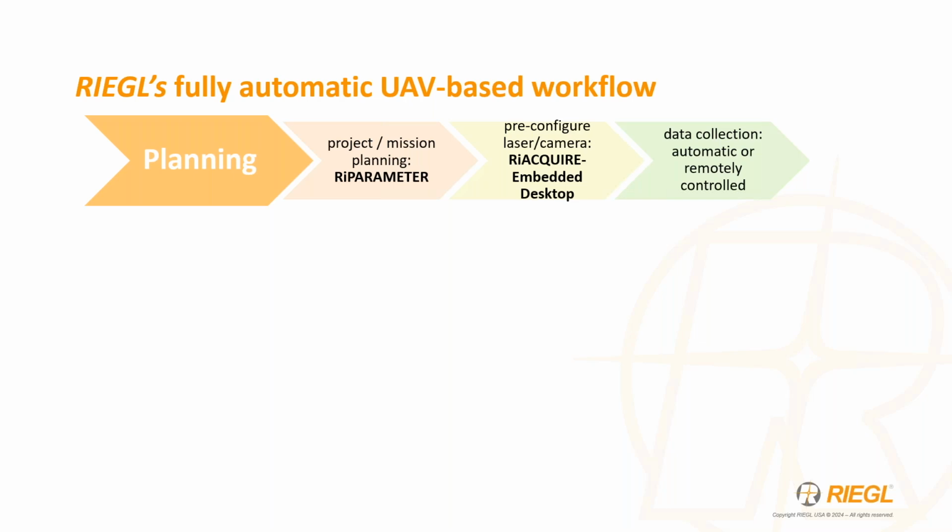And then using the parameters of that mission, you can use RIEGL, which is our free software. You can toggle, based on your scanner type, the laser pulse repetition rate options for that particular scanner and scale it accordingly based on your AGL and the area, and make sure that you're capturing the point density that you need to collect that information. You can feed that into RIEGL Embedded, which is our onboard embedded acquisition software, for all of the laser parameters that you've determined from RIEGL.